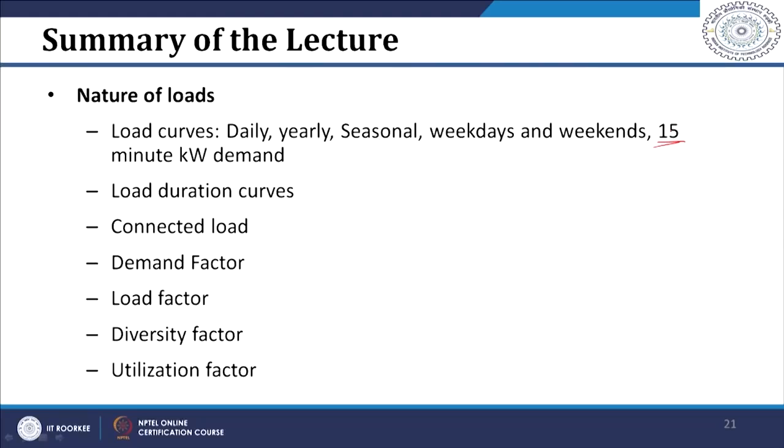Then we saw load duration curves, basically to find out overloading or utilization of your equipment. Then we saw various factors: connected load, demand factor, load factor, diversity factor and utilization factor. And we have seen that load factor and diversity factor are very important from the point of view of the utility. Thank you.